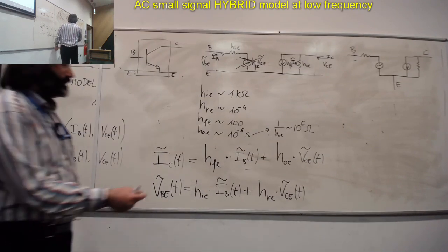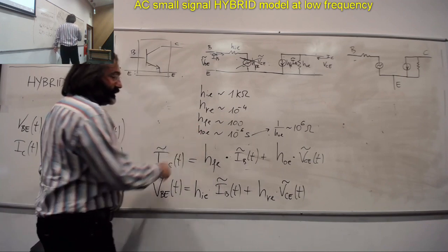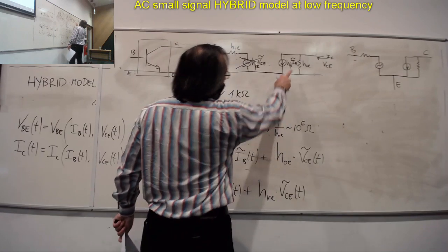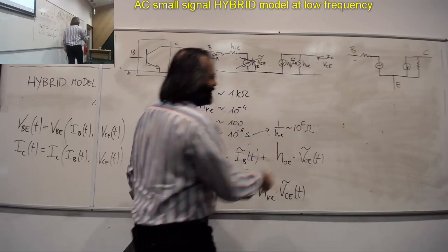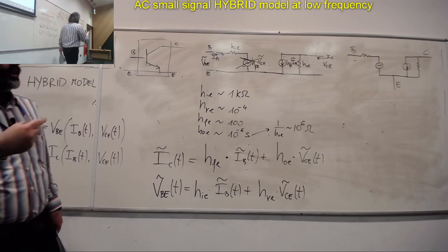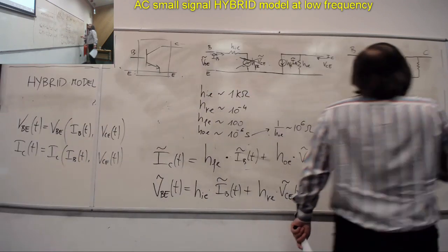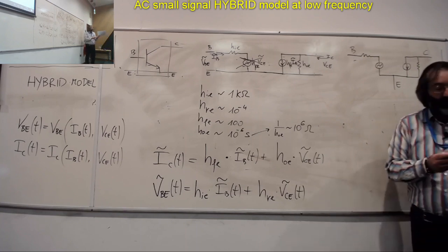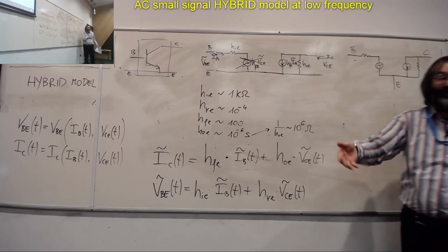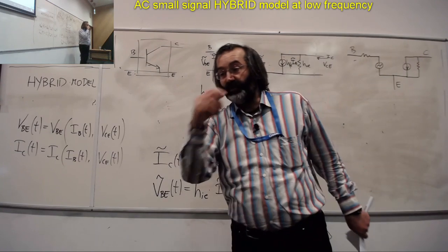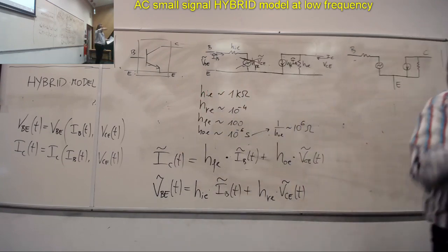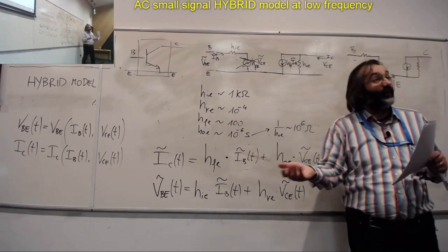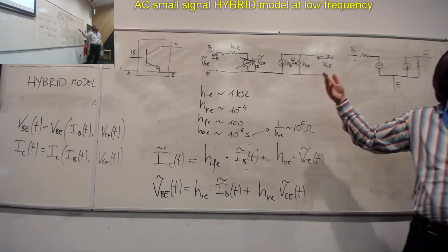The other thing is HOE. So this resistor here has 1 over HOE, which is the resistance, 1 mega ohm. 1 mega ohm is not a huge resistor, but it is also not very small, isn't it? We generally deal with resistors as we've seen last week, if you remember when we did the analysis of the DC biasing and so on. And the resistors we dealt with were in the order of kilo ohm. So this is definitely much bigger than that.